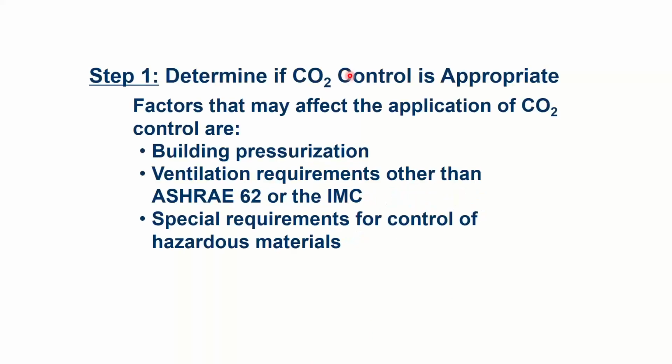All right, so if you're doing a project, you've got to figure out if this is going to make sense for you. There are things you have to pay attention to other than just the people. For example, if you have a lot of outside air intake because you need to pressurize the building because you have a lot of exhaust fans, like in a laboratory or something, this might not be the best thing for you, right? Because you can never go below a certain amount of outside air when you have a lot of exhaust fans running. So pay attention to those kinds of requirements and things that are going on in the space.